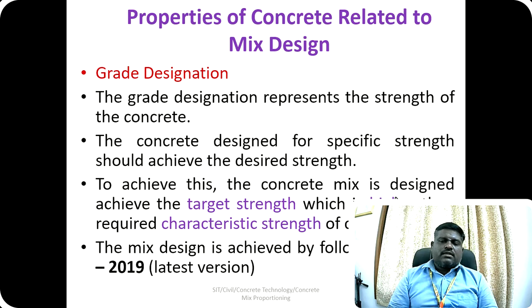To achieve that, we have to follow the concrete mix design code IS 10262-2019, which is the latest version. They framed a detailed procedure for achieving a required mix proportion for concrete with OPC cement, with blended cement, etc. So based on the recommendations given in the IS code, to achieve the concrete mix,